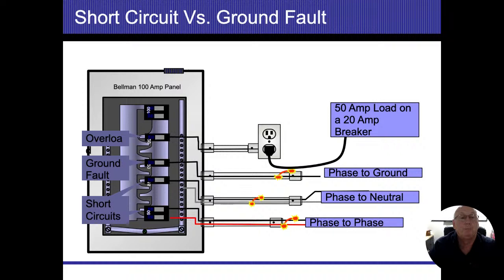On the bottom, there's a bar that connects my 2 neutral bus bars, and you'll see a green screw in there. All right. So on the bottom, that green screw actually goes right into the neutral bus bars where that metal's connected to it. It goes through the gray or black plastic insulation. The insulator is the black plastic so that it separates my ground, my neutrals, and my energized conductors and my bus bars. It keeps all those separated. And then it keeps going all the way into the back of the panel. So it screws into the panel.